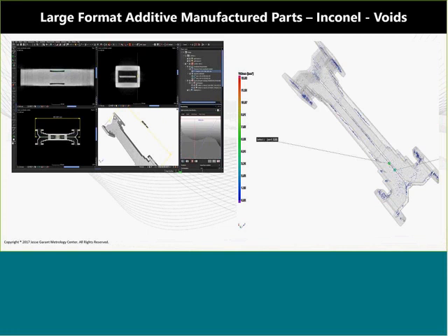Okay? If you give anybody a part that's 16 inches in size, you can't say that you want 2 micron resolution. It just doesn't happen that way. It's physics. There's no technology that will allow you to do it. If you wanted to measure a flat plate, CT is not your answer. That's a CMM.